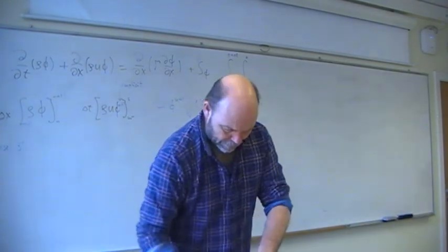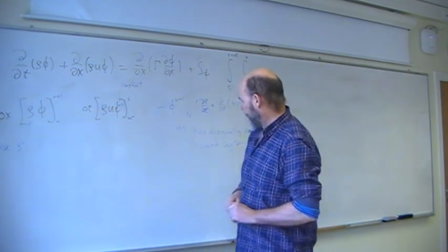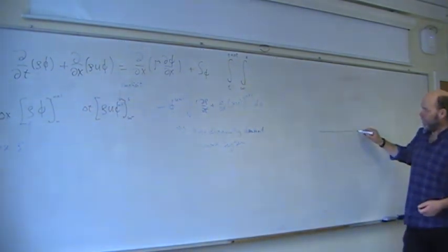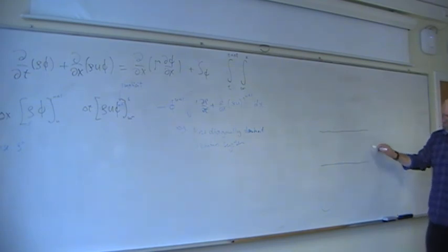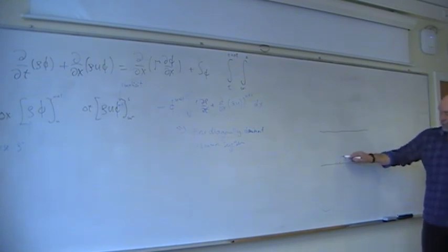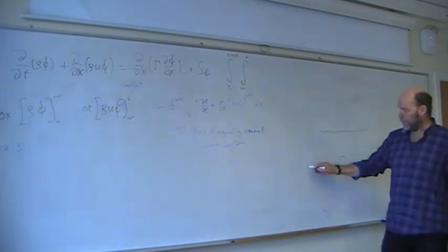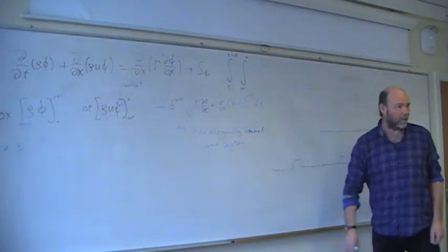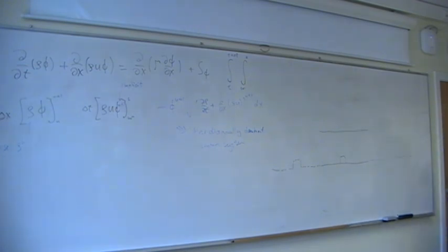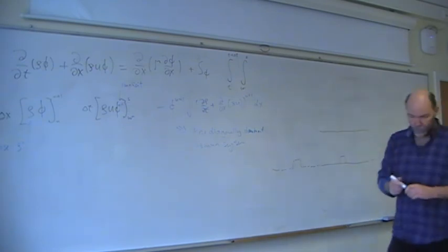You said you had a channel and you wanted to use periodic boundary conditions here. And the channel has the corrugated wall, and in each part it's a repetitive structure. So you only take one bump or something. Yes, that is quite obvious. Yes, you can take periodic boundary conditions. How you want to do it is your choice.